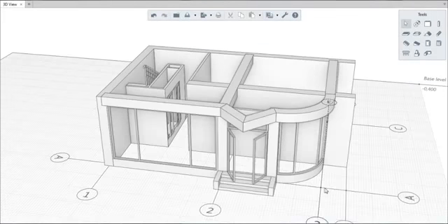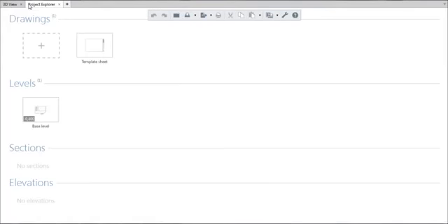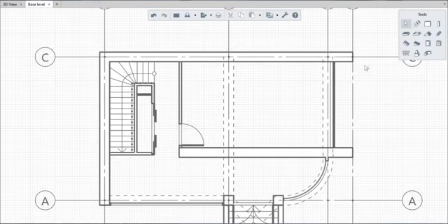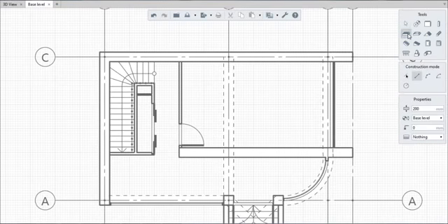To create a slab on the floor, create a new tab in Project Explorer and then open Base Level. Select the Floor tool, set the thickness to 400 mm and level to 400 mm, and then proceed to pick points to define the slab.